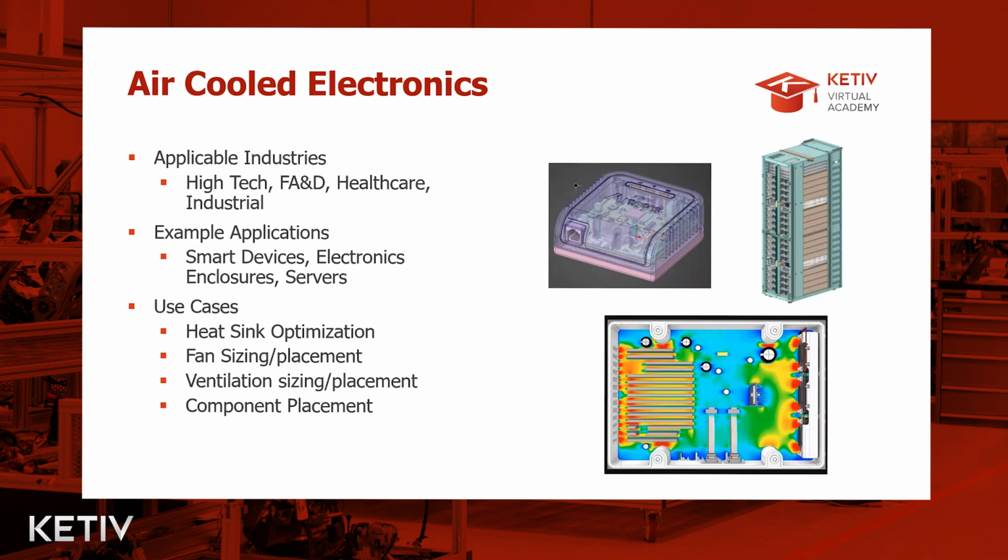But most commonly in this space, Discovery is used for heat sink optimization, fan sizing and placement, ventilation sizing and placement, and component placement. Because it's so easy to change the geometry on the fly, you'd be able to look at various permutations and combinations of your design and see which one works best for you. So with that said, let's jump into the demo.